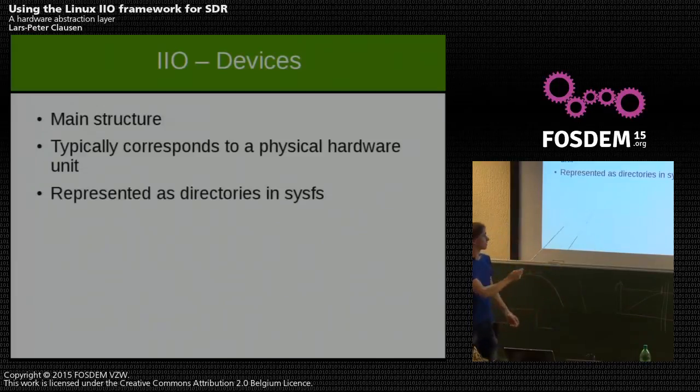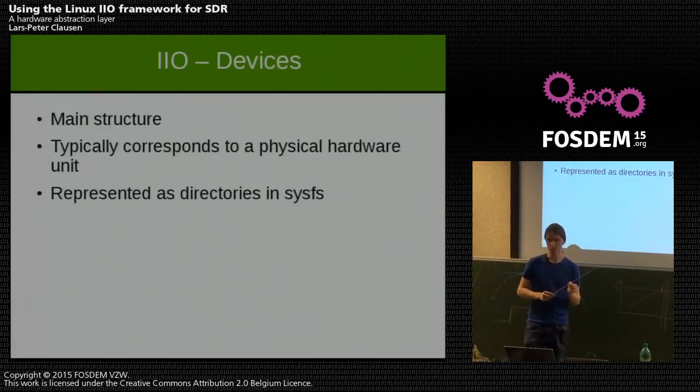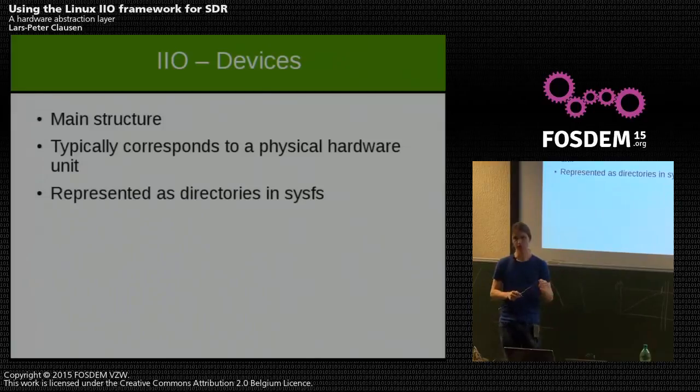And these I/O devices are represented in sysfs. Does everybody know what sysfs is? Who doesn't know what sysfs is? Okay, a few people. So sysfs is, I can actually show you. Oh, well, I will show you later. But it's basically a virtual file system provided by the Linux kernel, which is exposed to user space, which you can access with normal file open and close system calls. You can read and write from it, and this is what is used by the I/O framework for configuration of devices.